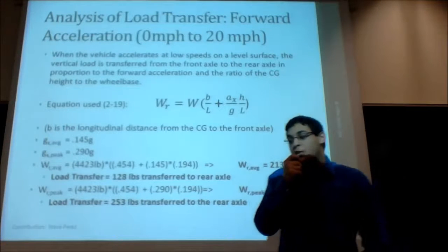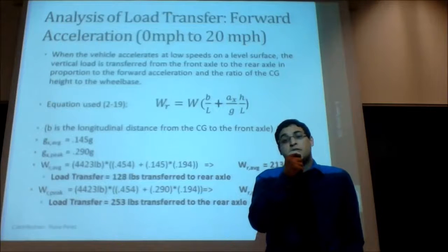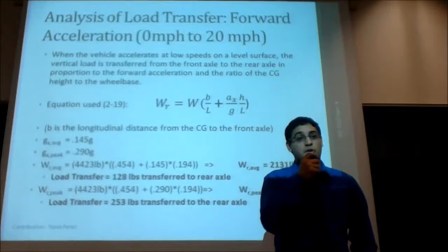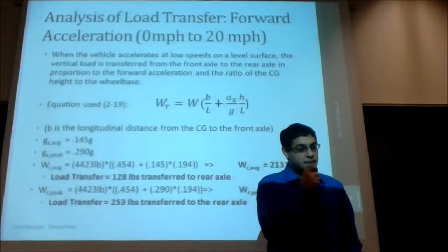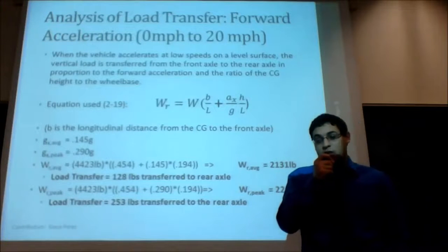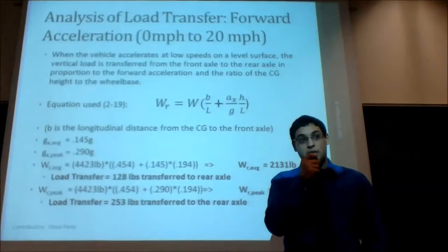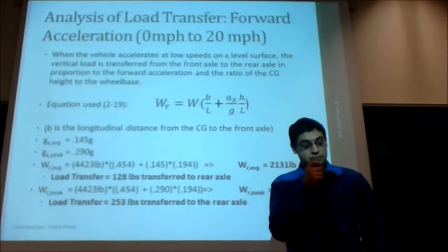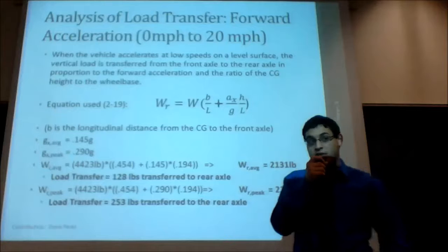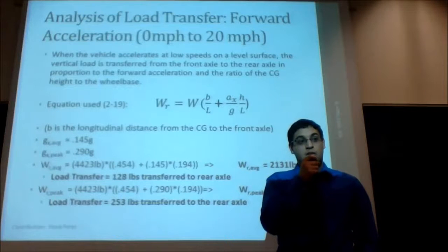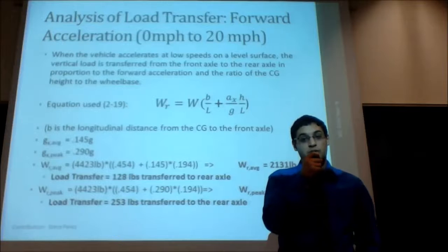So when you're accelerating in your car from 0 to 20, from 0 to any speed, you're going to feel a force of you kind of being thrown back into your seat. The same force is going to be felt by the tires. The rear tires will feel a greater force than the front tires during this acceleration. After steady state acceleration, once you achieve a steady state velocity, you will not have this load transfer anymore.